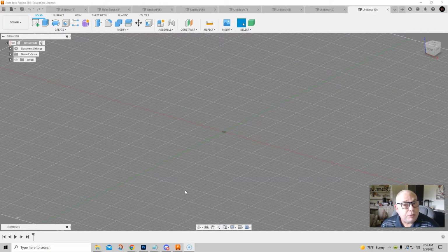In normal subdivision surfaces, if you're in something like 3ds Max or Maya, everything that you're doing has to be quads, or a few triangles in there too, but anything more is evil. You can't have 5-sided, 6-sided, everything is evil. It's just quads and triangles. Now, in Fusion 360, it's a little bit more robust in that you can have triangles, quads, and 5-sided are legal too. So 3-sided, 4-sided, 5-sided.